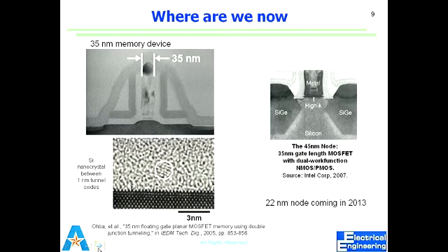And what's a wafer? Probably should bring it next time. So in the labs, what you will be using will be a 2-inch wafer. It's a circular disc of silicon which is 2 inches in diameter. We use 4-inch wafers also. Industry uses 8-inch wafers, 12-inch wafers, and now they're using 16-inch wafers. So it's a big plate of silicon, 500 micron thick, and we have to make devices all over it. So that's the kind of uniformity we need over the whole substrate, a few nanometers.